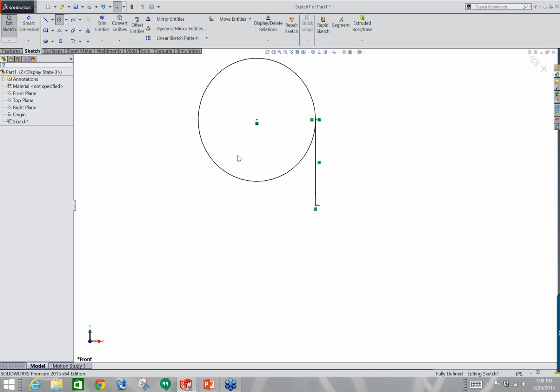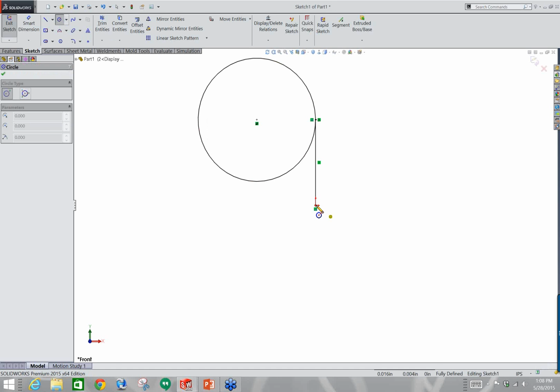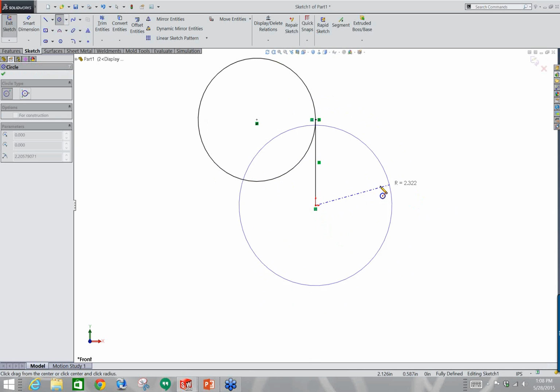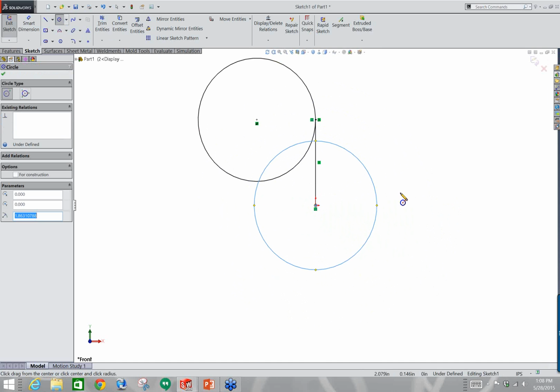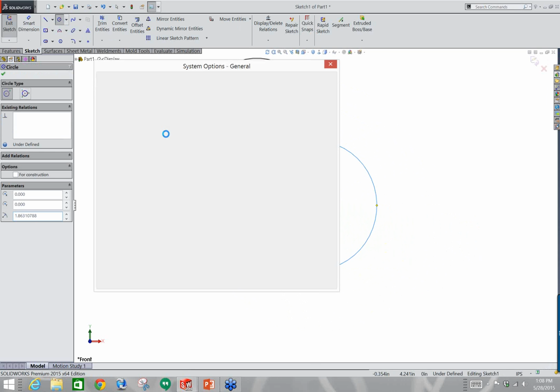Okay. Another thing, when you come in and actually go in and sketch, let's say, a circle, normally as I drag my sketch out, I just can drop it anywhere. But if I want, say I want to get it to drop to, when I'm coming in and want this guy to go to specific increments, I can. All right, it's not doing it for me. Okay, hold on one second. Usually when we're drawing a sketch or a line or something, we can get the actually, I know what my problem is. My snaps haven't been set. Sorry.